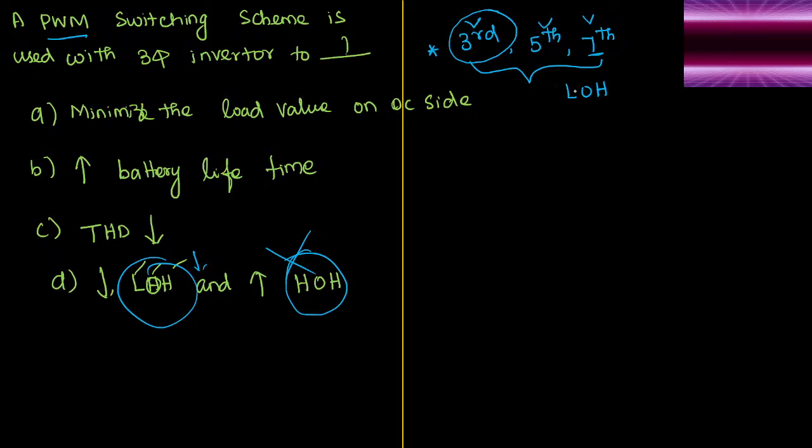Its magnitude also gets suppressed, and its effect becomes insignificant. If you go to the 9th, 11th, 13th, 15th order, continuously increasing the order of the harmonic, suppose I take the 51st order, because even harmonics will be eliminated. The 51st harmonic has to complete 51 cycles within 360 degrees. See that its effect is almost insignificant, sir. It is negligible. Why should I bother about it, sir?